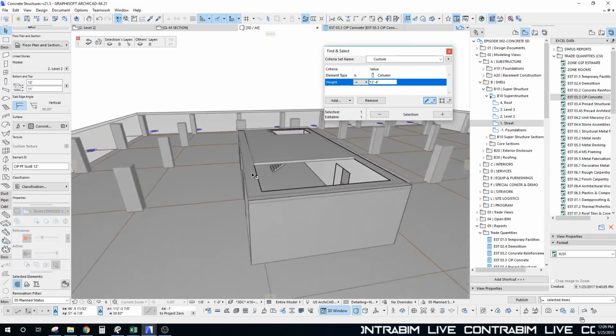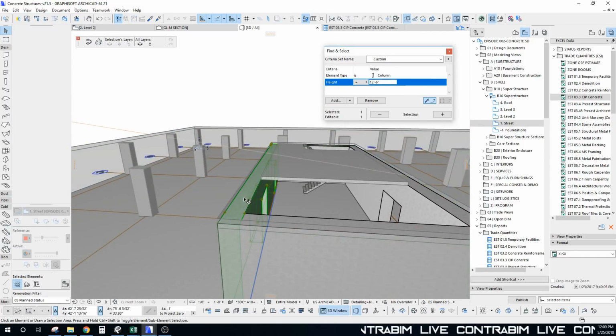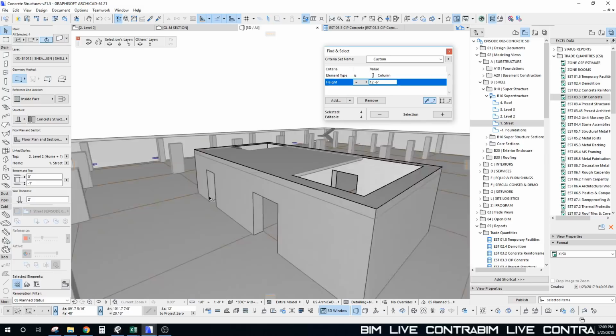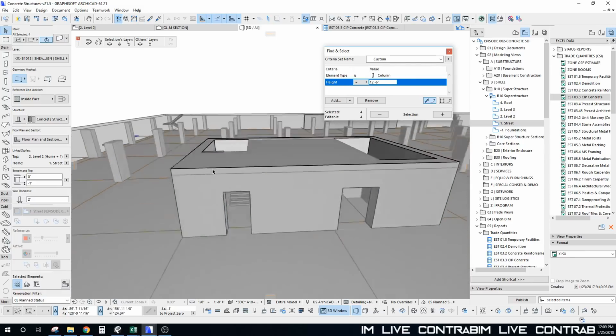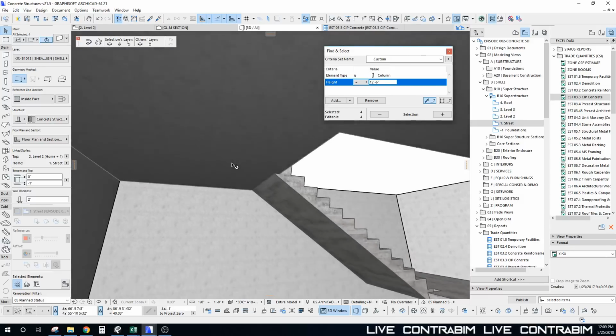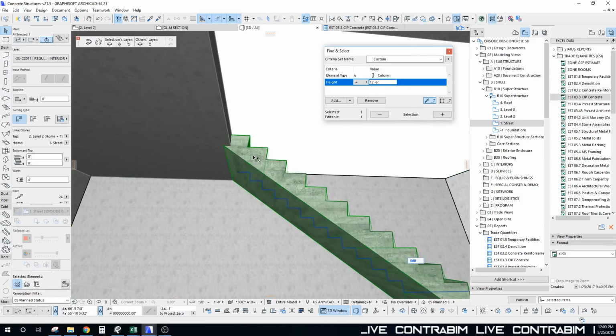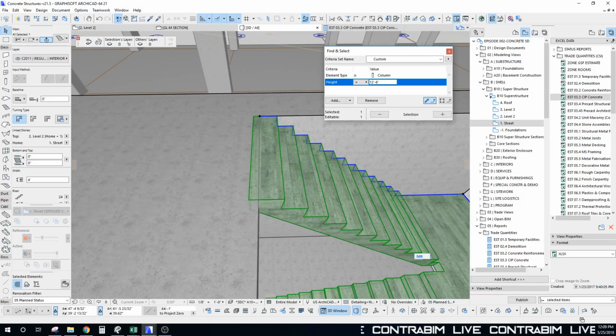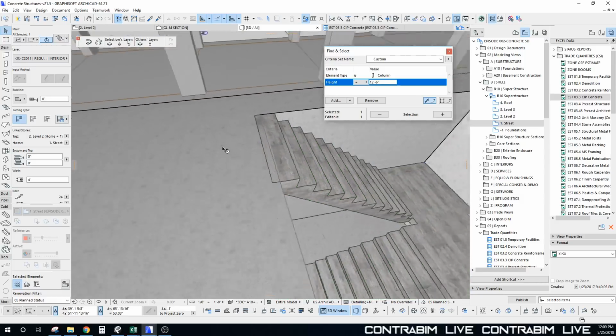purposes. And so these walls here, what I actually need to do is I'm just going to select all those and we're just going to zero that out, because that now is a full floor to floor. So there's always a little bit of cleanup we can do. With this particular element here, we can see there's a little bit of overlap, but that's actually overlap that's built into the stair element itself.